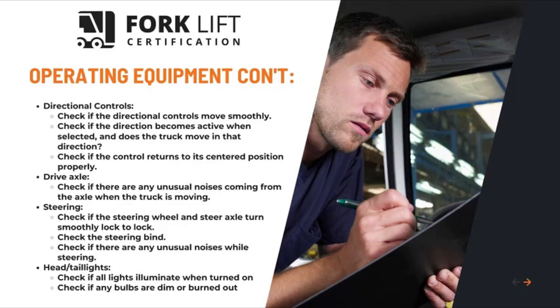Drive axle. Check if there are any unusual noises coming from the axle when the truck is moving. Steering. Check if the steering wheel and steer axle turn smoothly lock to lock. Check the steering bind. Check if there are any unusual noises while steering.